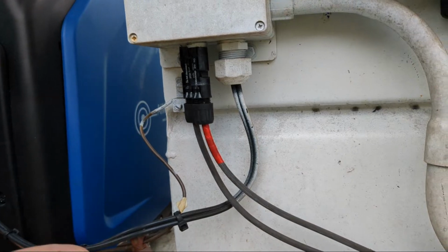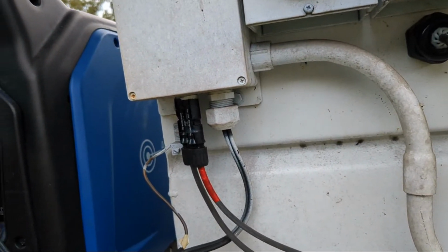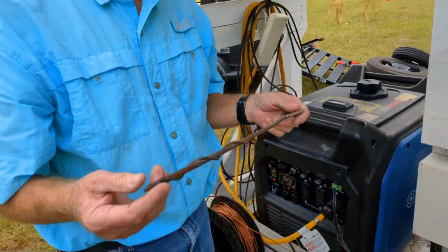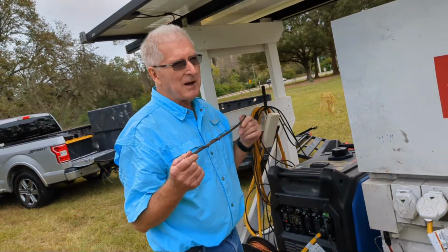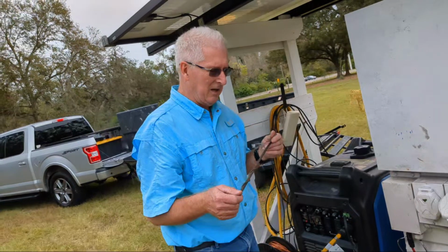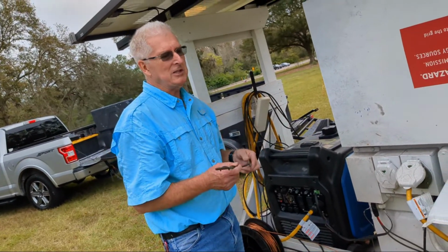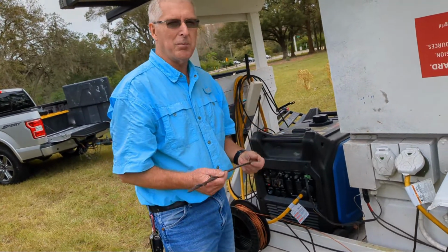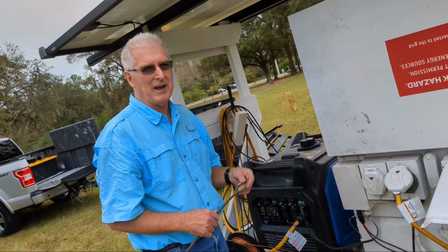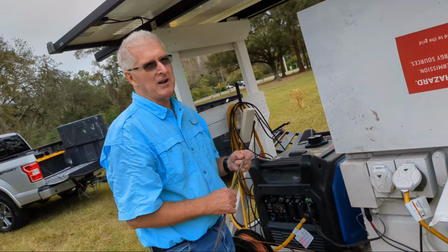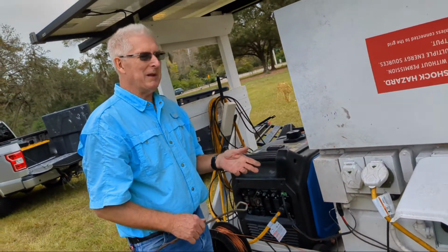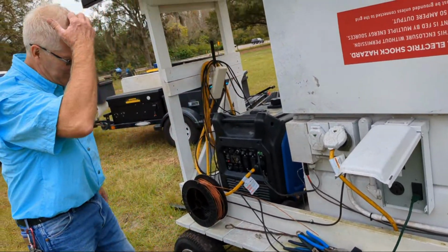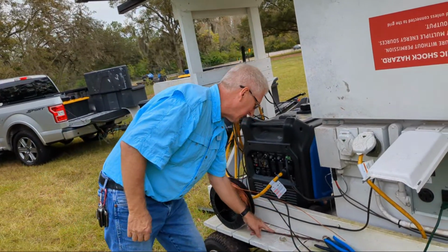I'm going to take this copper line and bond this to the rod, which is really inadequate. This should be like 6 feet long, but having said that, some connection to earth is better than none. I'm also worried in this application about someone forgetting we have this bonded to earth, and just driving away. If I drive a 6-foot rod in the ground, it's going to pull everything off of here, and that's probably not going to be good. Anyway, I'm going to go get some parts that I need, because this connector is not going to be big enough to fit around this temporary.